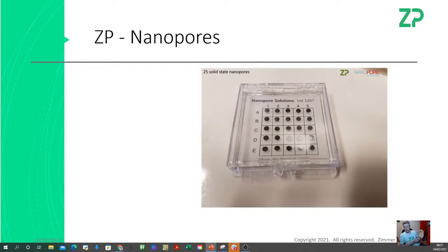And you get a very small current because basically 20 nanometers is like a massive resistor. But as interesting molecules like DNA go through there, they end up blocking the hole for a brief second, and the impedance jumps up. If you're very clever, then depending on the bases, whether it's an A or a G base, you actually get different profiles.